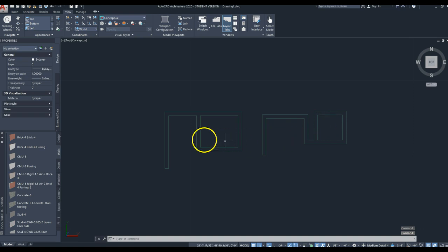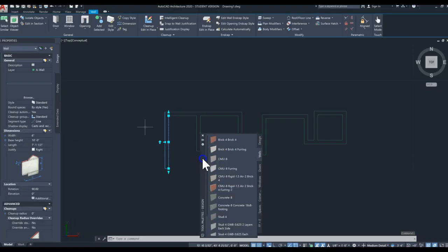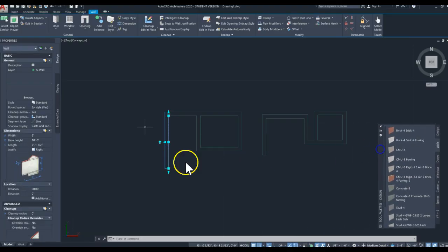Okay. So we know how to build walls. We may have to change properties of those walls. So let me hover over this guy and click once. Now this is in the way, so let me move this perhaps to the other side. Okay, look under dimensions. This is where you have the width of the wall. Maybe it's not 6 inches, maybe it's 4 inches. So you type in 4 inches there and you hit enter. And look, your wall is now thinner.